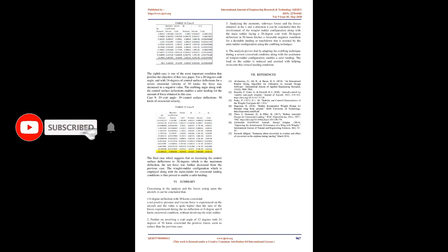6. Summary. Concerning the analysis and the forces acting upon the aircraft, it can be concluded that 1. With 0 degree deflection and 30 knots crosswind, a net positive pressure and viscous force is experienced on the aircraft and the value is quite higher than the sum of the forces experienced during the no deflection or 0 degree and 0 knots crosswind condition, without involving the mini-rudder. 2. Further on involving a crab angle of 12 degrees with 24 degrees deflection and 30 knots crosswind, the positive forces seem to reduce compared to the previous case.